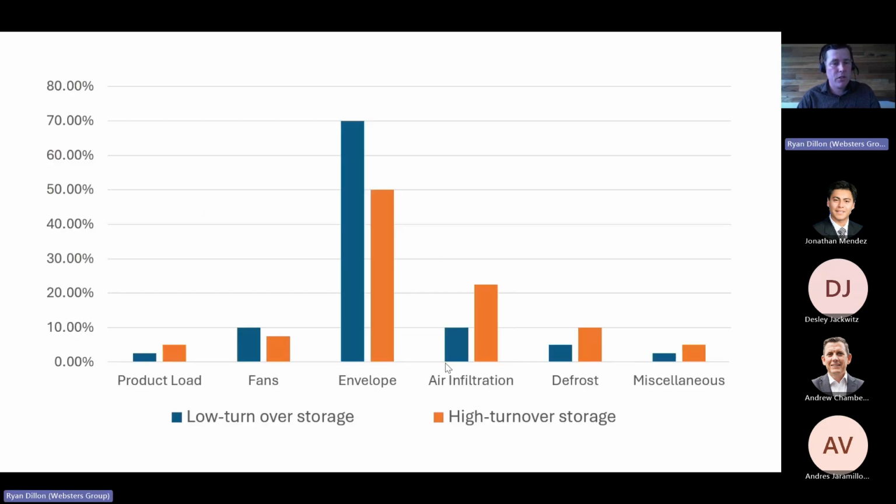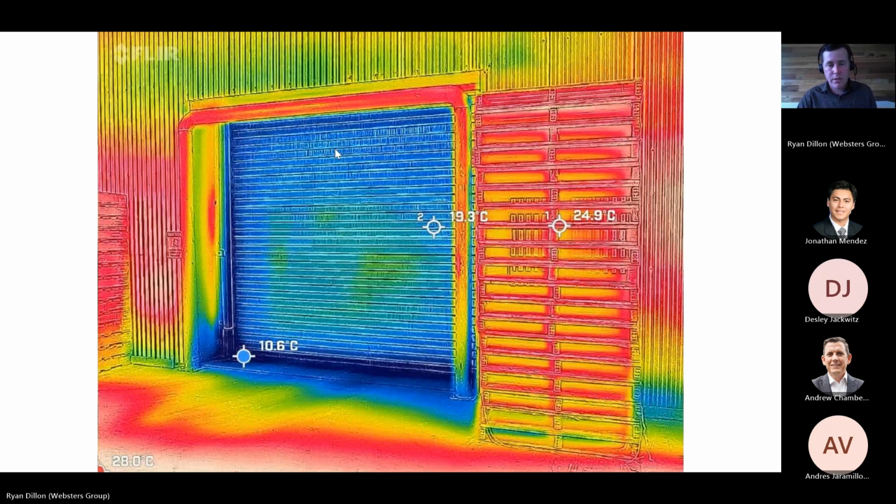And that's kind of a summation of where we're looking at these 50 to 70% heat losses that need to be rejected year on year in your cold room. So I'd mentioned the door strips just prior. They have that thermal envelope and the radiant component, but if they're not providing a correct seal, we also have air infiltration.